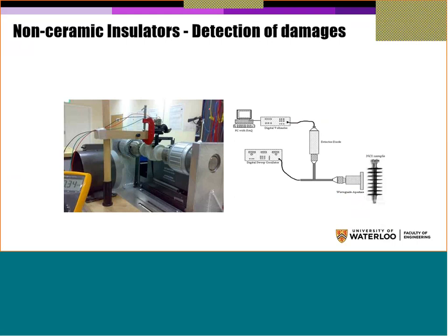So what we are trying to do here is a different way of inspection using very high frequency, called a near field sensor. In the near field, we have a waveguide, and this waveguide sends very high frequency that is reflected back. This is taken and rectified, and we get a sort of DC voltage. Based on the dielectric constant inside the fiberglass, you will detect a different signal.